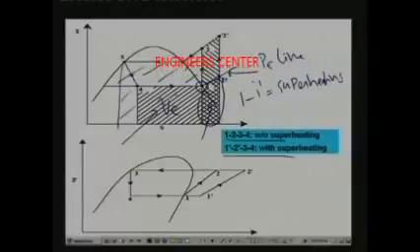So what is the effect of the superheating? First effect, immediately you see that there is an increase in refrigeration effect, and that increase is given by this area. Okay. So this is the area which is an indication of increase in refrigeration effect because of superheating. Okay. And there is also another effect.